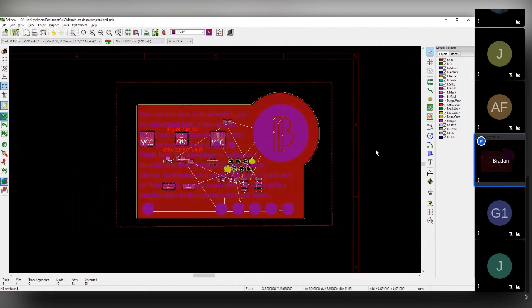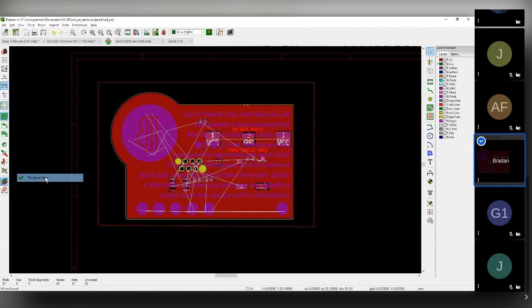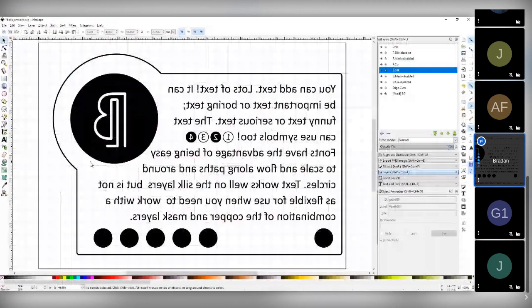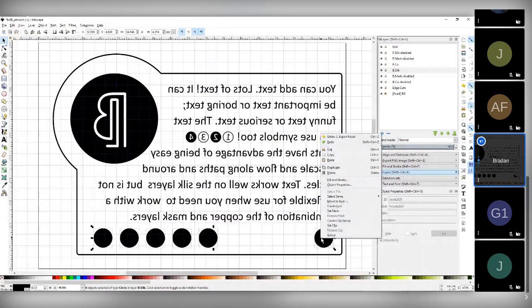But you'll notice that if I actually look at the copper layer, I didn't clear any copper out. All I've done at this point is just simple artwork. So now if I want to actually clear out the copper on these, let's go back to Inkscape here. There are a few tricks, so I'll just do these down here since we're running long on time. Let's say I wanted to remove these from the mask and remove these from the copper layer. I'll do a quick duplicate.